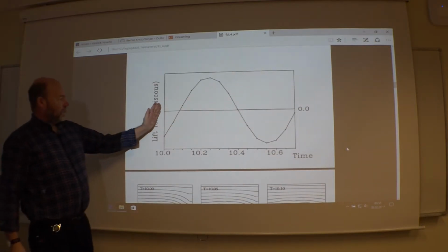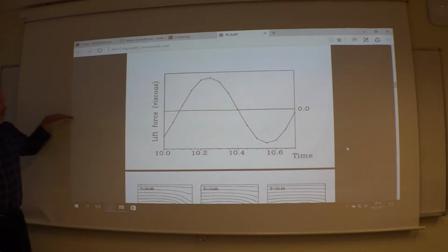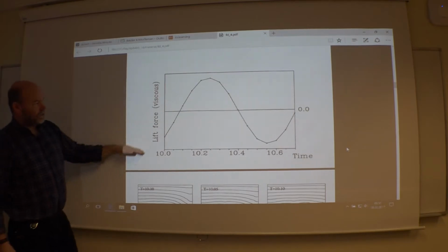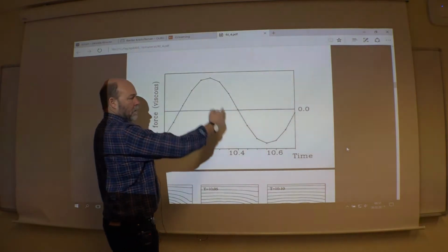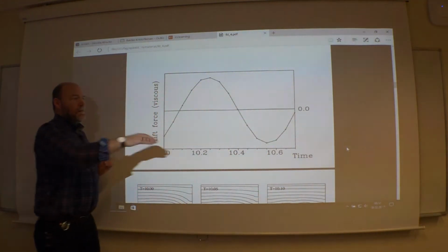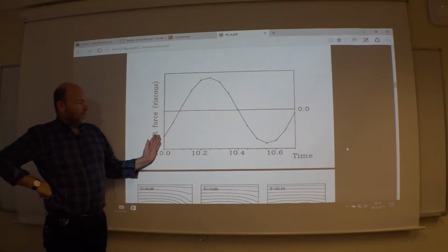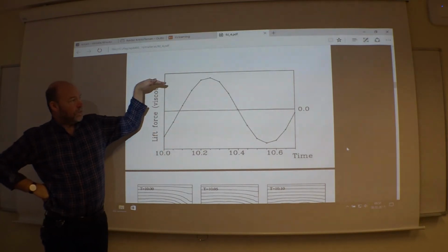If you had plotted this lift force all the way from time equals 0, he would have started as 0. And then he will slowly start, and then finally he should be established. So you have to simulate long enough so that this one is constant periodic from here on, or else it's not a steady state, a steady motion, so that the amplitude is constant.